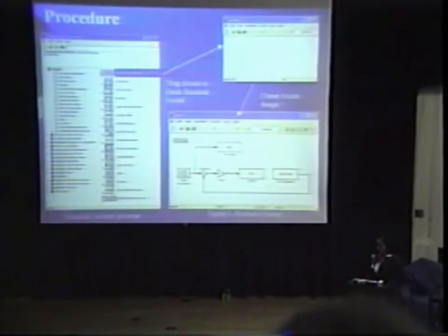This is the procedure to create a model in Simulink. First, you open the Simulink library browser and then select the blocks that you want to use. Drag them over to a blank model window. Then just create the design you want. The design shown in Figure 1 is a model created to operate the servo system, focusing on position control.